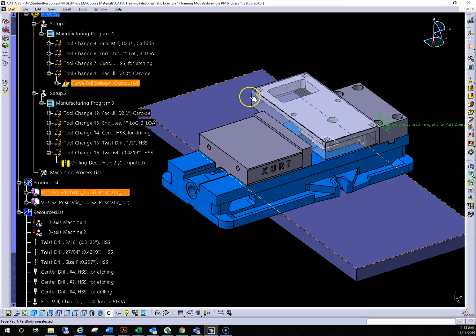In this video, we're going to work through how to move toolpaths that have been generated in CATIA into Vericut for verification. Through the assignments that you've been following, you've been using models that have been created for you. In this tutorial, you're going to see how to build a model. To do this, we're going to utilize a direct interface application that ties CATIA directly to Vericut.